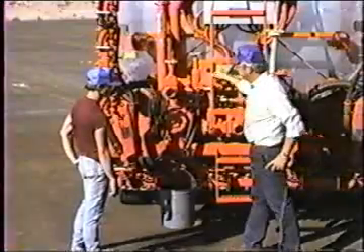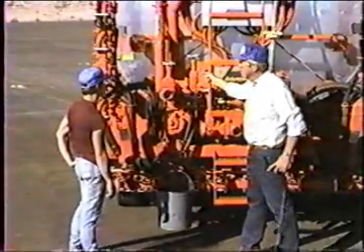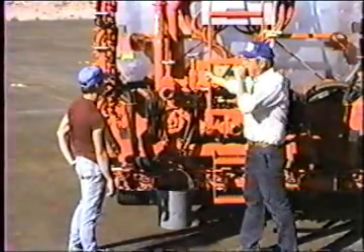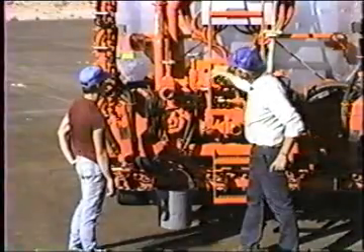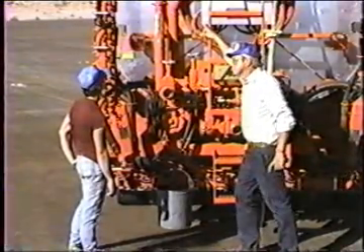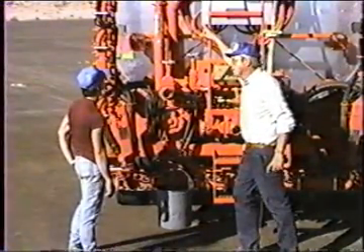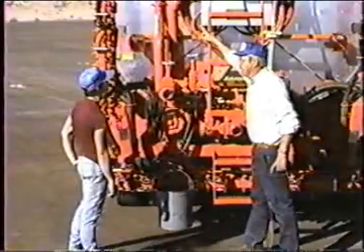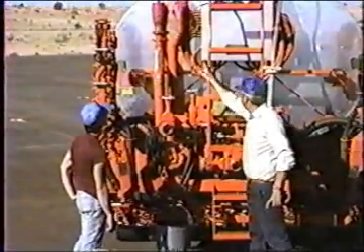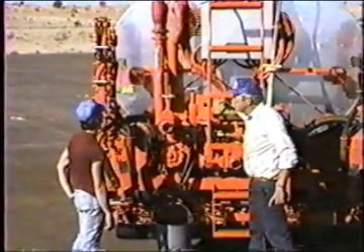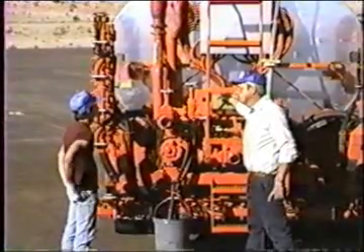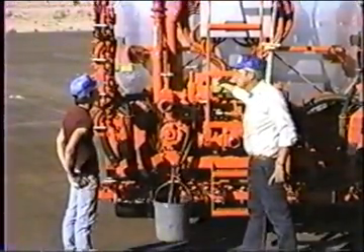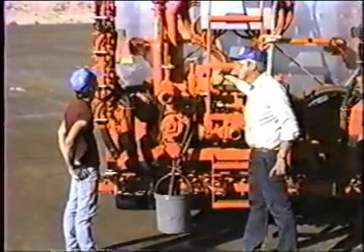Okay, it's got one other place it could go very freely right now. Excuse me. The relief valve is open. It's free to go back into there. Okay, we don't really want it to go back in there, and we've made provision for that. On the master switch, the rear master switch on the control panel here has a flush position. Put that down to the flush position.